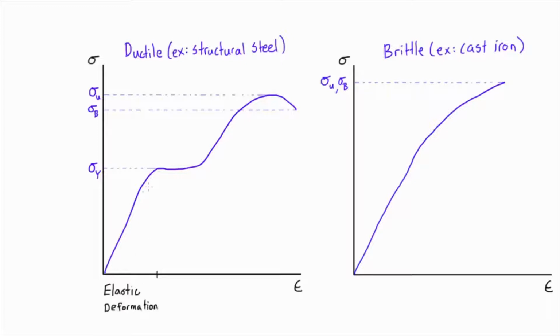And we call that elastic behavior or elastic deformation. And in this region, Hooke's law applies. And for those of you that, if that's new to you, Hooke's law here is stress is equal to capital E, this is the modulus of elasticity, times the strain. So there's a linear relationship between stress and strain in this first section here, so long as the material has not yielded.